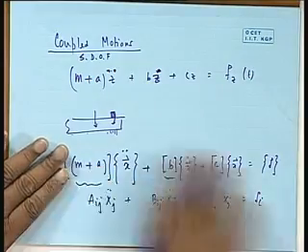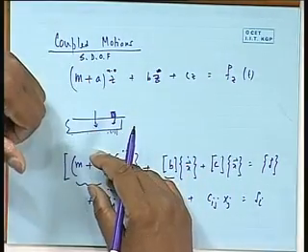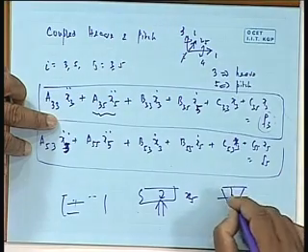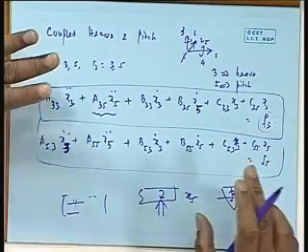You see, what I wrote beforehand is a general one, where you are assuming without knowing that every motion is coupled with every other motion. We will find out that for a ship, because it is symmetric about the center plane, heave, pitch and roll are coupled, and surge, sway and yaw are coupled, because when you give a heave it gets pitched also, and when you give a heave it can also roll, because when you try to heave it or when you roll it, it will cause a heave. So roll, heave and pitch get coupled actually.